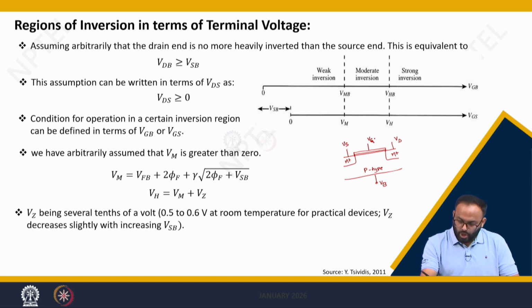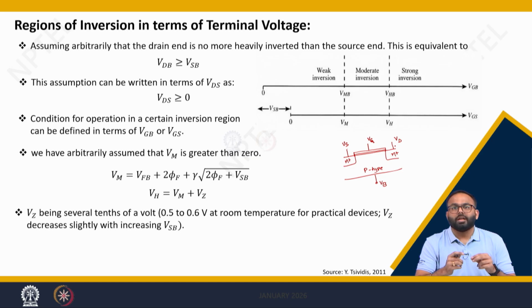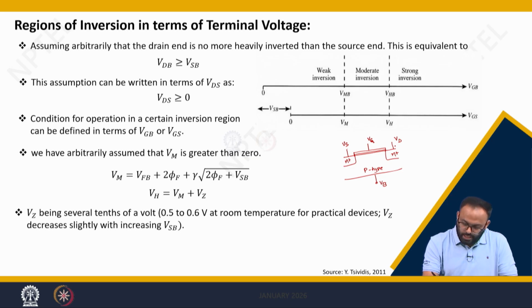We have discussed thoroughly in previous lectures what common reference you are taking, that matters a lot. Suppose I am taking the body as reference, I can simply say I am applying a voltage VDB where body is my reference. However, there is also a possibility I can take the source as a reference, so I can apply the voltage between drain and source.